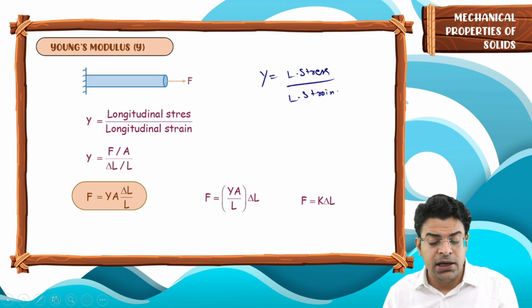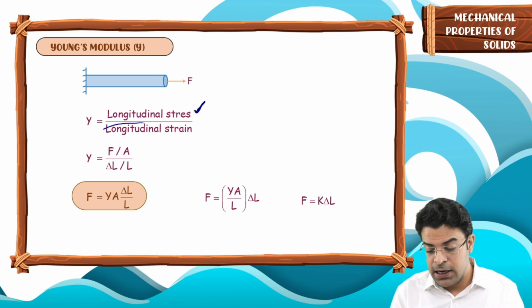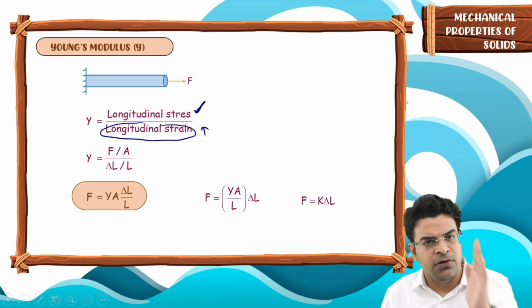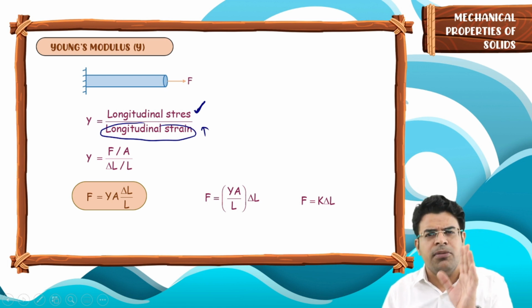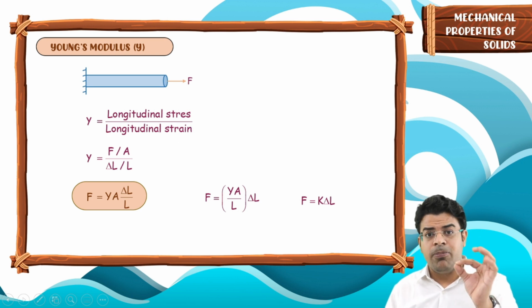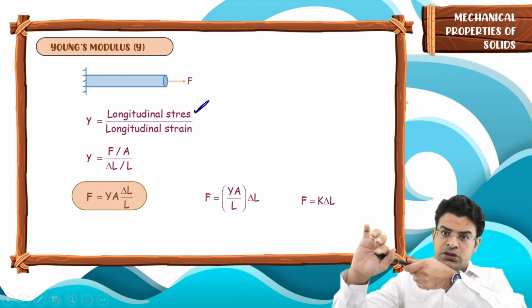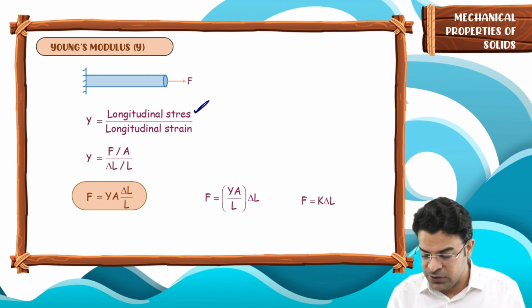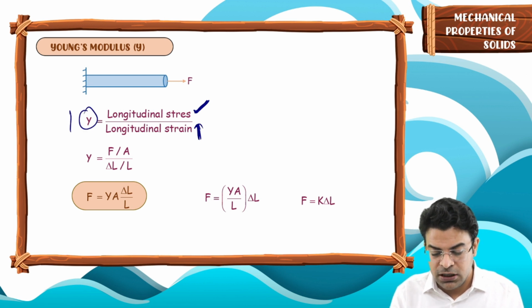So if you heat up an object, then for the same value of stress you get more strain. Here chemistry is involved. It doesn't work for 100% of objects, but it works for many of them, right? For the same stress, the same force per unit area, the strain will be more. It elongates more. So the strain increases. The stress is the same, the numerator is the same, and the denominator increases. It means that the Young's modulus decreases.